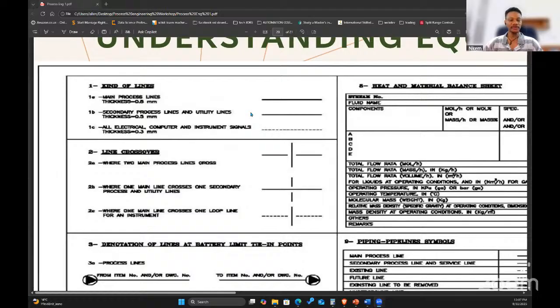You need air to control the pneumatic valves, and you need your electrical signals to send either an analog or digital signal to the valve to open and close the valve, or to vary the valve according to whatever the process is. So all these lines will tell you what this is doing at this point in time in the drawing, and this is exactly what you're going to find in the field.